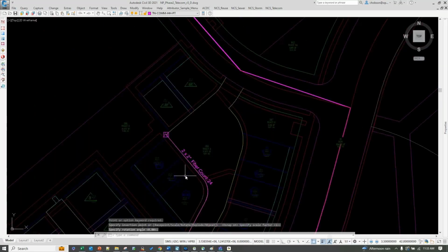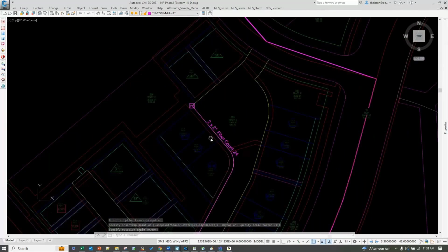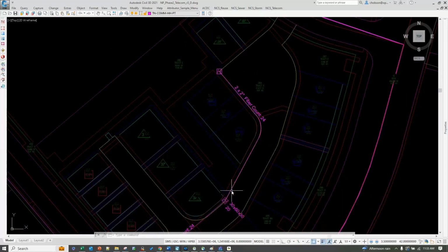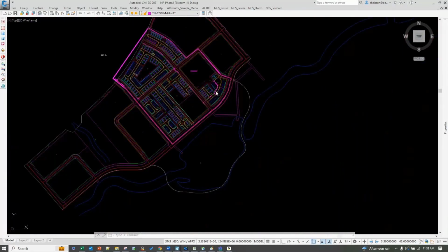I don't want to spend all the time on all the CAD nuances, but you get the point that line features need an attributed block, blocks need their own attributes. So there's a handhole with the properties: 20 feet, 20 slack, and the size and whatever. But this drawing is going to fail because I've set that up. You can have all sorts of things in the rules that we check. I'll talk about that in a minute. We actually advise that you detach the XREF before you submit the drawing. So I'm going to do that quickly.